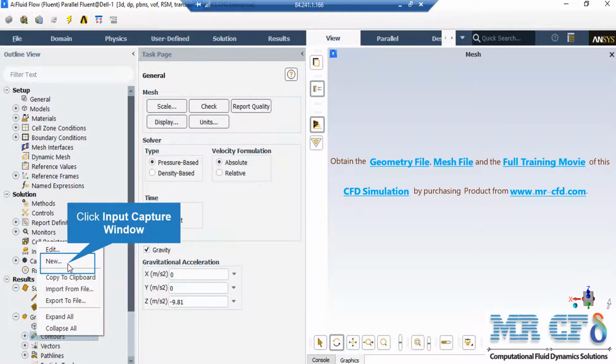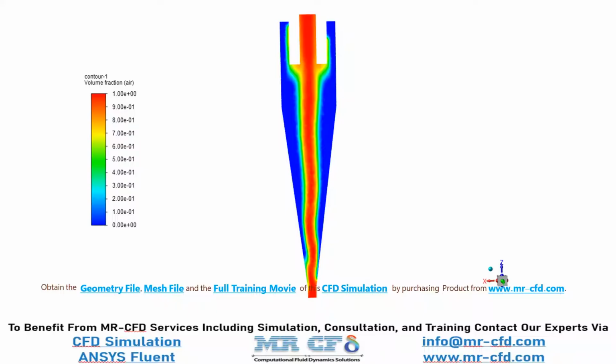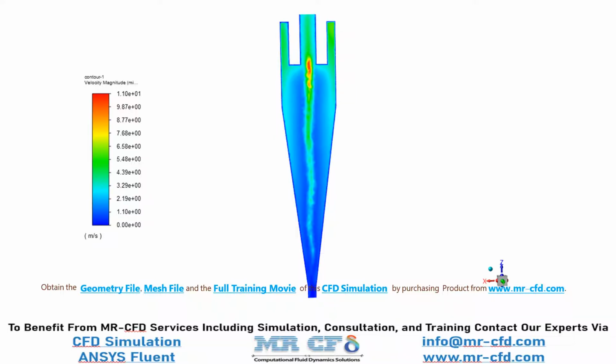Now after defining a plane, we go over the contours and right click on it and then select New. Now in this slide, you can see the contours of volume fraction of air, and you can compare this contour with the contour presented in the paper. It should also be noted that just like the paper, there is an air core in the middle section of our geometry. And in this slide, you can see the velocity distribution in the middle plane of our geometry, and you can compare this contour with the contour presented in the paper.